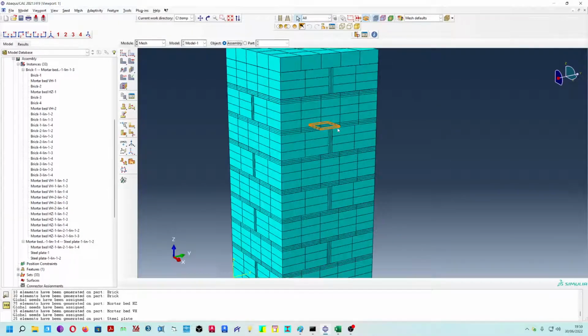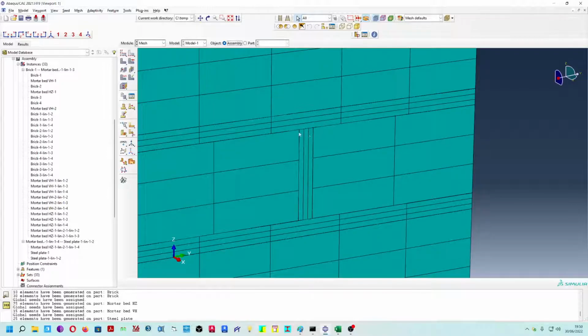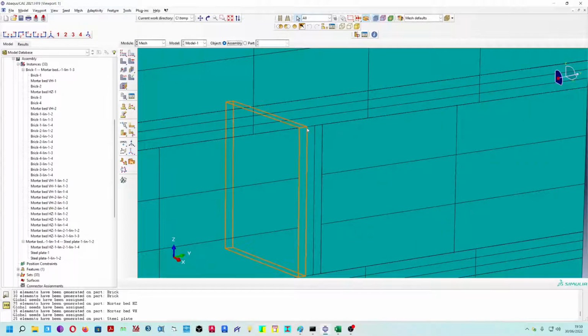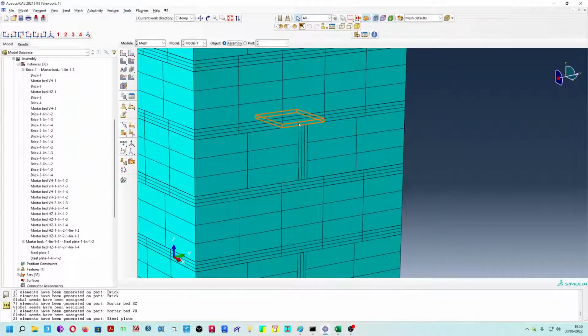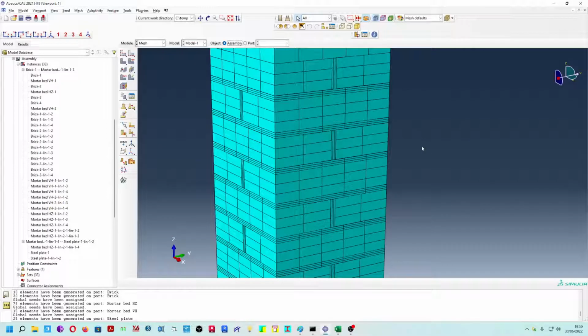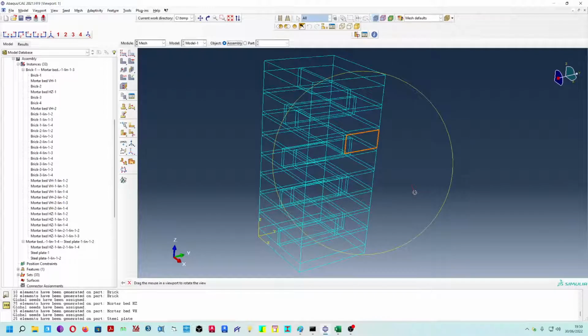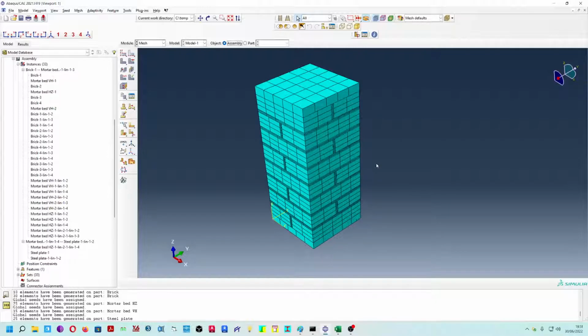we are. Now, do not be worried that the nodes of the mesh do not connect to each other. It's not a problem in Abaqus. I mean, I read something like this. It's not like SAP 2000 and other finite element software.